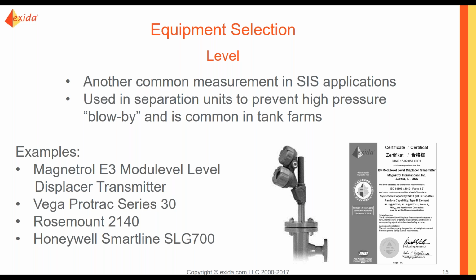Sensors are available as either level transmitters that send a proportional analog signal or level switches that send a Boolean value. Both types of products are available, and with 2-wire 4 to 20 milliamp interfaces. Level switches are also available with contact switch output.